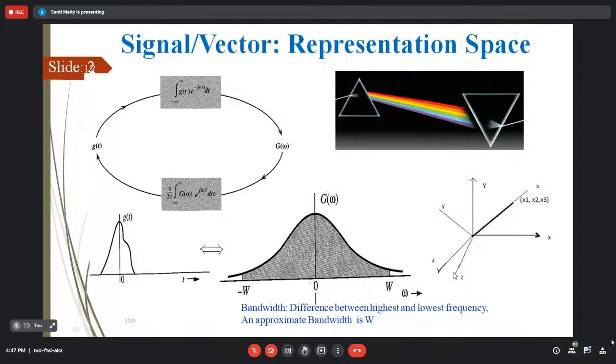In a sense, the frequency content goes on decreasing, and that suggests that okay, you may not have the full reconstruction of the original signal, because for perceptual data, your audio, your speech, your video, you need not go for complete reconstruction. As long as the intelligibility is okay, that's fine.